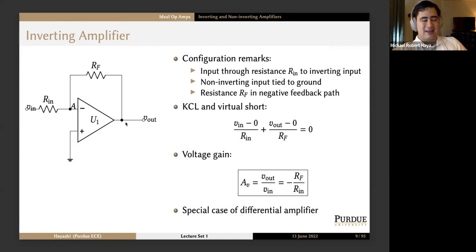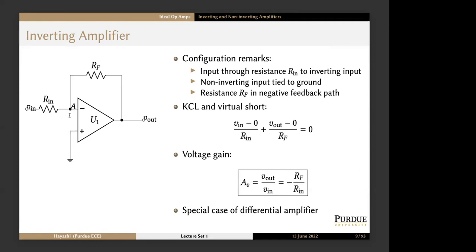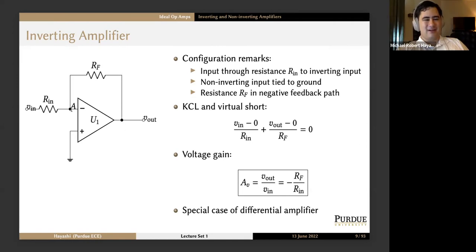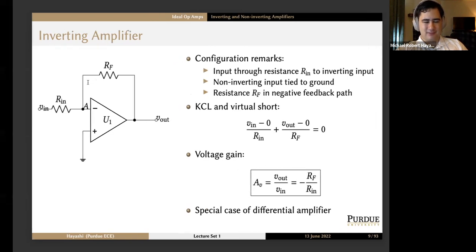So the op amp is going to do everything in its power to make these two potentials the same. That means there would be zero potential difference, and 0 times infinity is an indeterminate form, so that allows you to have a finite output voltage. Did that explain your question, Suraj? Yes. Thank you. You're welcome.